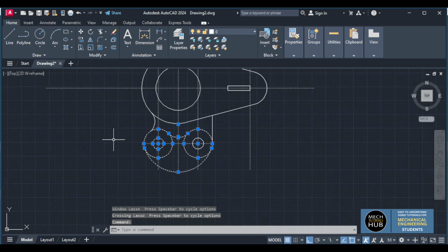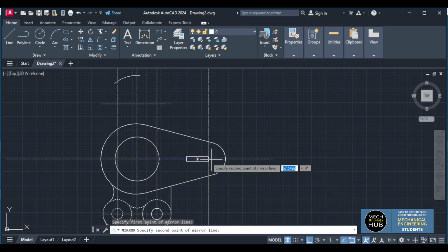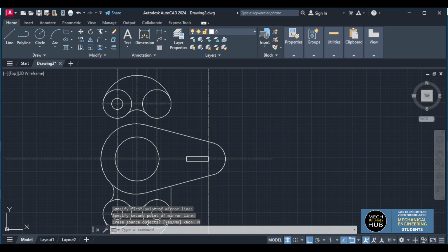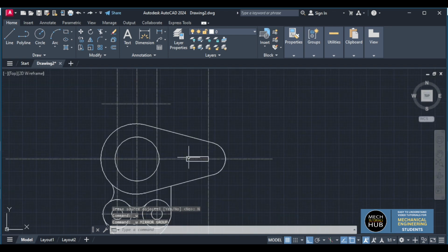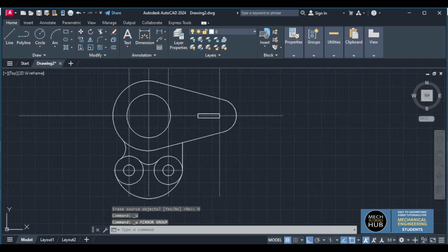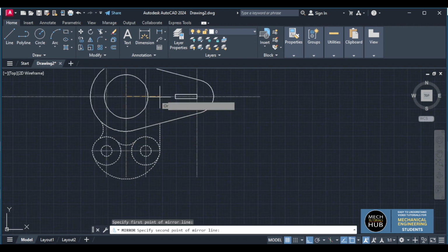Then I select mirror with respect to horizontal, then yes, no, I'll say. Oh, forgotten to select this one, Control Z, Control Z. The circle is not selected. Let me go individually. This is okay. Circle, line, curve, these two, this one also, this curve, mirror with respect to this line, note it.